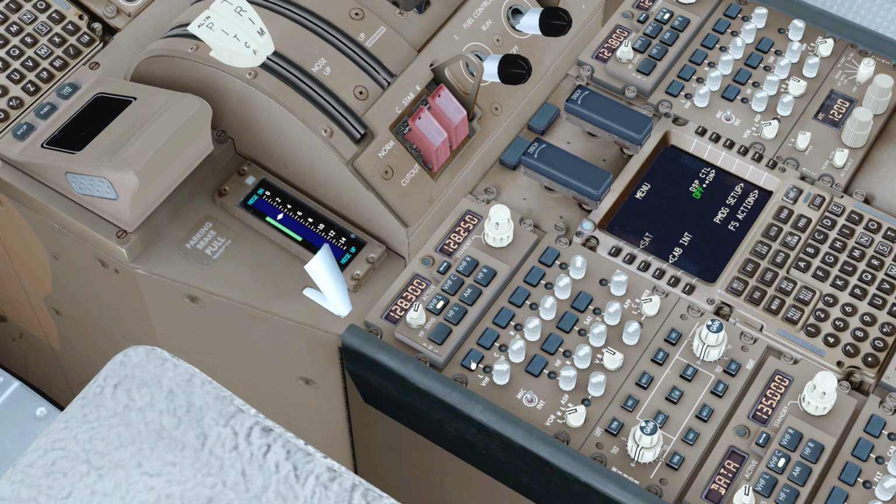VHF left is active, so right now your mic is working, and you can also turn on this switch in order to be able to receive the audio from the VHF left radio, which is this radio over here. So right now you can tune the frequency of your liking, and it will work on VATSIM. So if you ever notice, if you're starting from cold and dark on VATSIM and the radio is not working, make sure your microphone is actually enabled for the VHF radio that you're using.